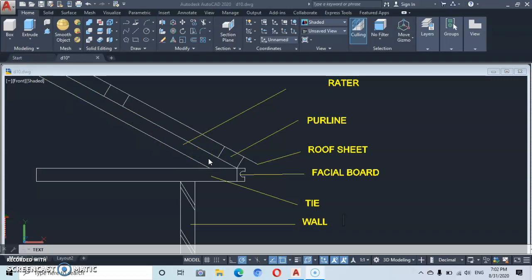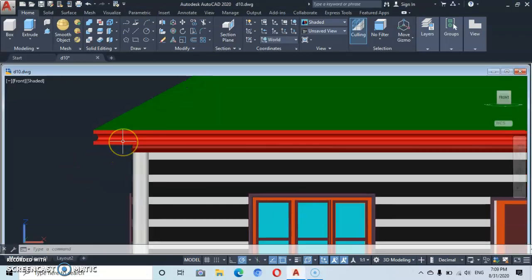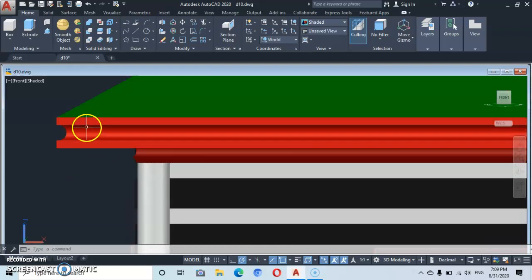So let's get back to our roof. Like I just explained, you will see here that this fascia board has covered almost all the beam, which is not supposed to happen. The bottom part of this fascia board is supposed to lie directly on top of this beam. So we have to move it upward to the right position. Let's go up here and we click.